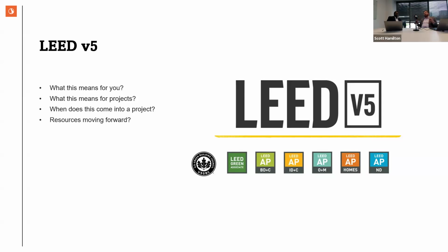Now there's scenarios where we can still pursue LEED with variances from the standard based on different adjacencies, based on over design, under design in certain scenarios. So a fun one would be partitions in offices. We love glass right now. It's in vogue. We want to use single pane glass. That is probably STC 30 to STC 35 construction. We need a privacy rating that is more akin to STC 50 to meet those requirements. And if we only look at STC ratings of partitions, you don't meet.